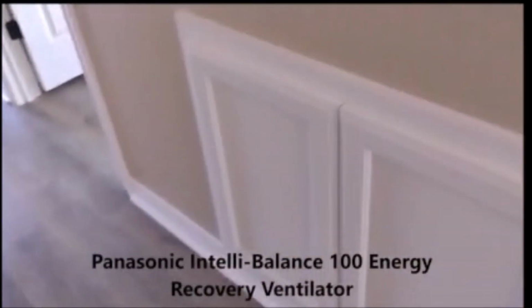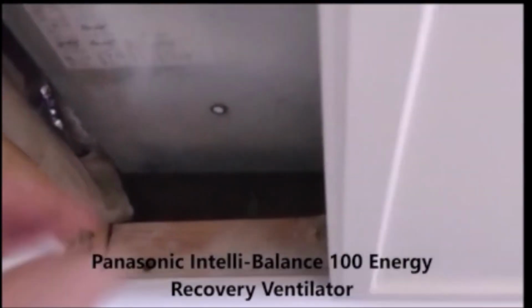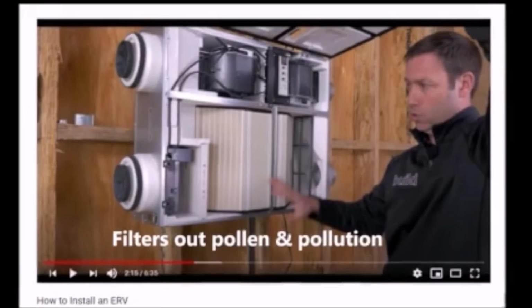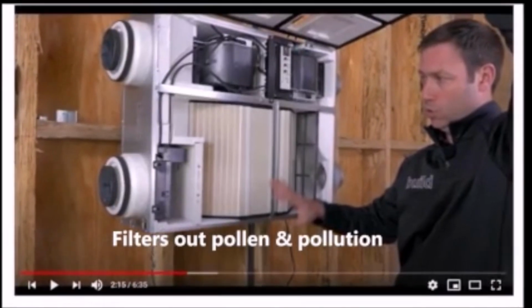And then for ventilation, as we said, energy recovery ventilator, we installed a Panasonic IntelliBalance 100 energy recovery ventilator for this 1,800 square foot, 9-foot high ceiling. Now you'll have to size yours accordingly, but it's accessible in the hallway, as you see there, with the controls. And as we know, the ventilation system brings fresh air into the house, because now we have the house airtight, as we showed before. And as we bring in fresh air, it's going to filter out the pollen and the pollution as it comes through the filtering system.